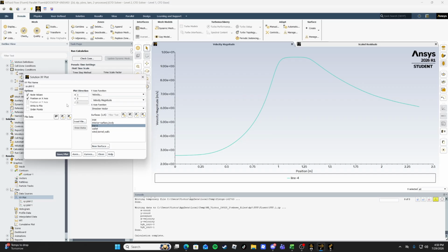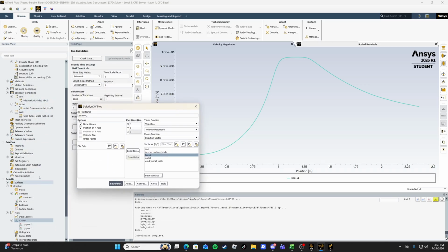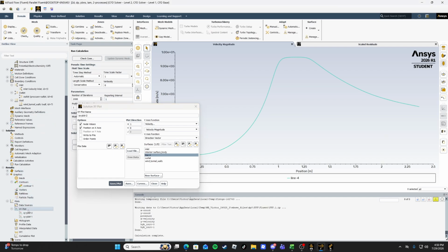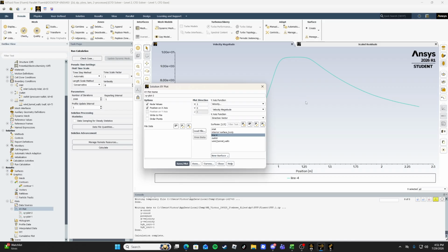So it'd be the same process. Just go back to the inlet, change the inlet velocity according to which hertz you're calculating, just initialize again, run the calculation, do the contours, get your XY plots by making the line rake surface, and that about sums it up. And then these plots you can export to Excel by writing the file, and just paste it into Excel, and yeah, that about sums it up for the setup part and everything for the project. So yep, that's my video.